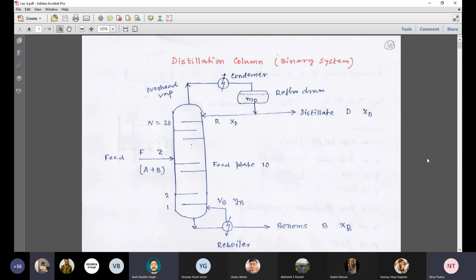When superheated steam is used in the ducts, it loses energy to the ducts because it is at a higher temperature. So there is a lot of heat loss happening. That is true, but at the expense of getting more heat, no? We are getting superheated steam by spending more, by consuming more energy, you are saying. But superheated steam is giving us energy at a higher temperature than saturated steam.